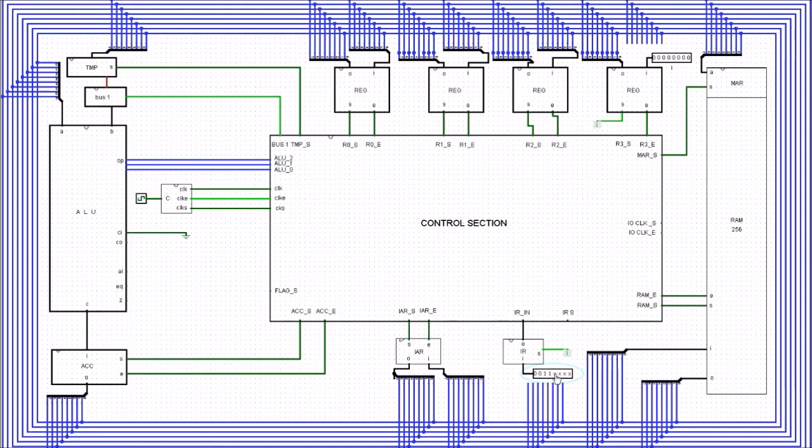The instruction we're going to put in for the jump register is going to be 0011. These 2 bits don't matter, they're not applicable, and the last 2 bits are for our regB, and we're going to choose the value 1, 1, which is register 3, which is this register here. So really what we're saying now is, instead of the instruction address register getting its next address via the accumulator, the instruction address register is going to get its next address from this register here.